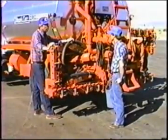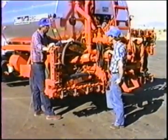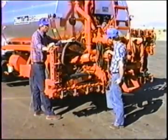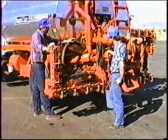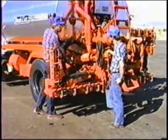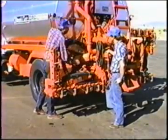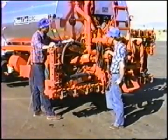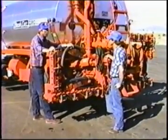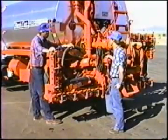It does all of that 32 times a second every second, so that it is continuously informing the asphalt pump as to the speed that it should be turning. Of course, in order to do that, it has to get its information. It has to see its travel speed from the axle housing, and it has to see the pump speed from the pump gear. Additionally, it must see the bar width from the control panel in order to have all the information to calculate the gallons per minute required.